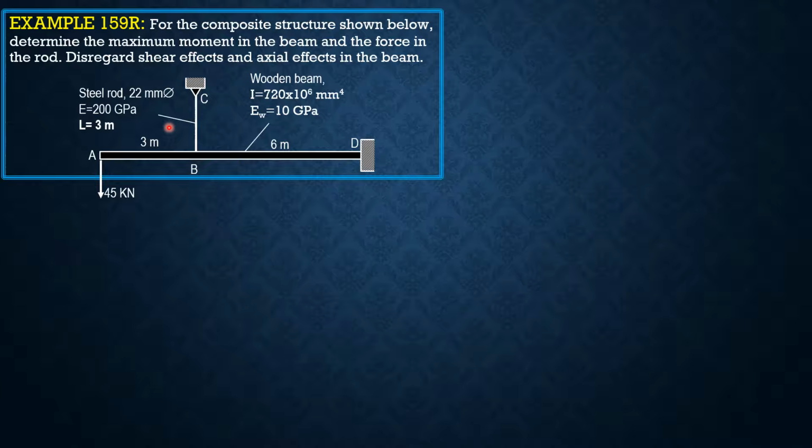So let's make the redundant force the tension force in BC as shown in the figure. Let's call that F. This will be our sectioning. There will be two sections only. So partial of U with respect to F equals 0.